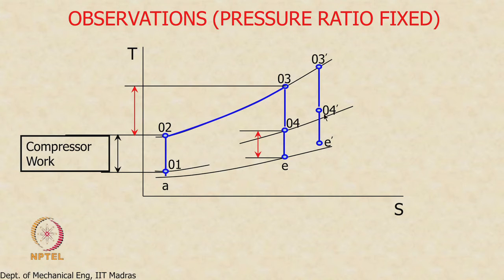So that means this is what I am going to realize as thrust. Notice that had the previous case been correctly expanded, this case would be under expanded. E prime will be more than E, because now I am up here at a higher temperature, and I am extracting the same amount of work, which means that 0.4 is going to move up, which means that E prime will also move up from E.